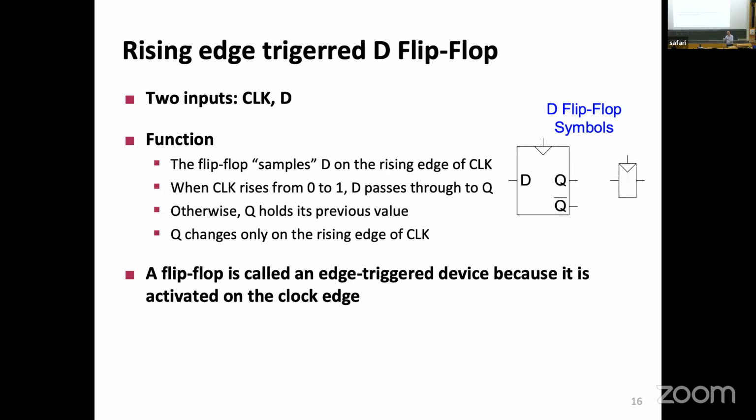I keep this value. Whatever I saw there, whatever the value was at the input, I keep it. Just that small instant where the clock is transitioning from 0 to 1. Well, how much is an instant? Well, 10, 20, 40 picoseconds, whatever. I need some time to memorize it, but not like half the clock period.